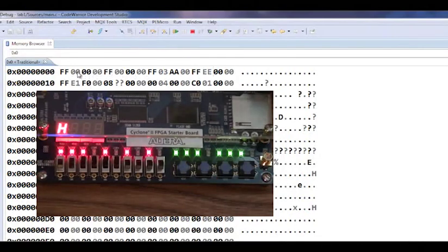So I/O is a little strange in that way. If you have a read-write register, it's very easy to see what you put in, but when you use a write-only register as on the 7-segment displays, you don't get that. Now we also have a couple of other things here, and these have to deal with our switches, our inputs. So far we talked about output devices. We've got 4 7-segment displays. We've got 10 red LEDs. We've got 8 green LEDs. And then we want to start dealing with our switches. And we're going to take a look at that next.